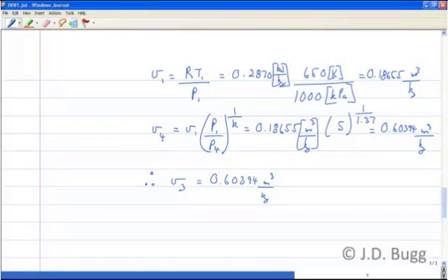Well, while we're at point 4 here, the other thing we can get is the temperature, because that'll be handy later on. So T4, and again, this is just ideal gas law. We keep applying the same thing over and over again. So we know pressure 4, we know V4, and we know R. So this temperature works out to 420.86 Kelvin. Okay? All of that stuff is known.